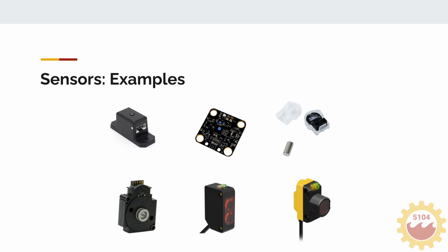It's also super simple to wire, and that's why I like it. Another one that's super nice to have, if you do use CTRE devices, is a Pigeon IMU. It's a super small gyro. This thing's maybe an inch long or a little bit bigger. You can hook it up with this port right here into a motor controller, like a Talon SRX directly, or you can run over CAN, and that's super simple also.